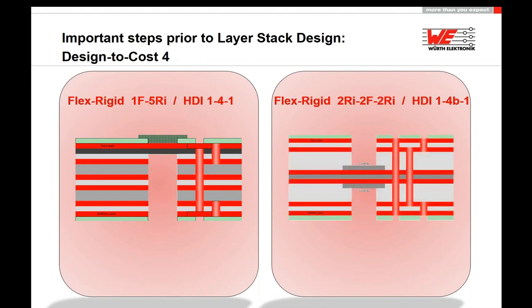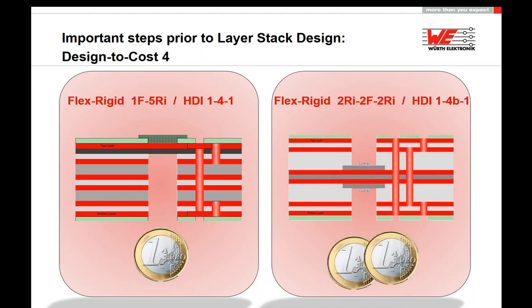And the next thing is to think about the option of folding, as you can see on the top right side: folding and then getting a straight flex, not needing a lot of area in the production panel. On the left model, the green model with the components on it, you can see the use of folding in different areas, thus getting a flat projection on the bottom side in black, which does not need a lot of area.